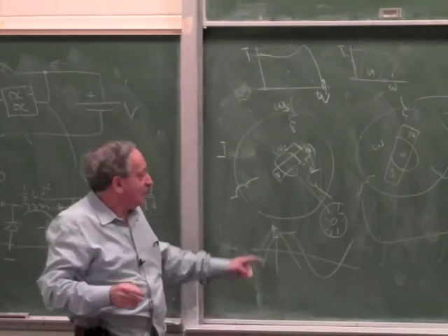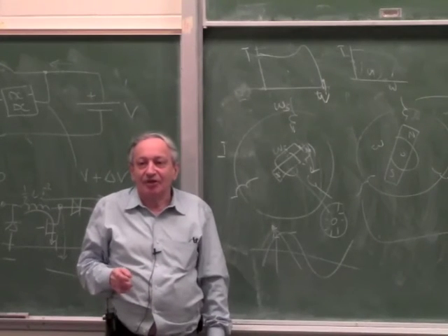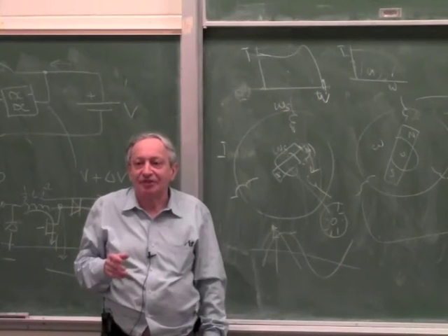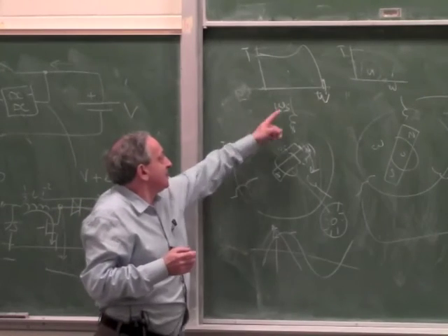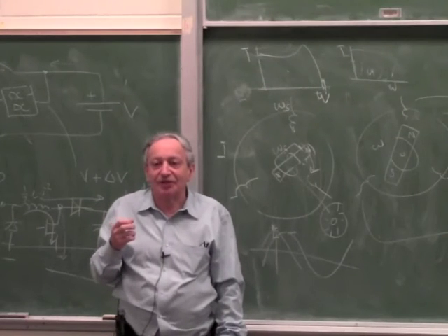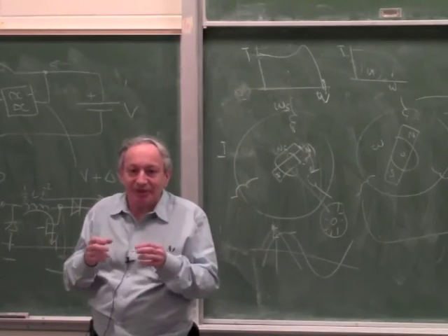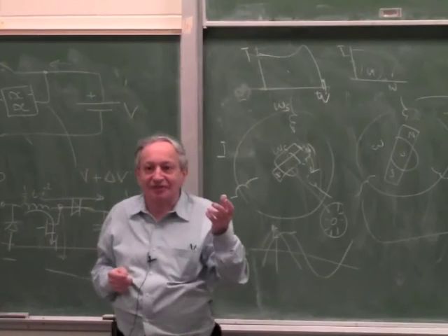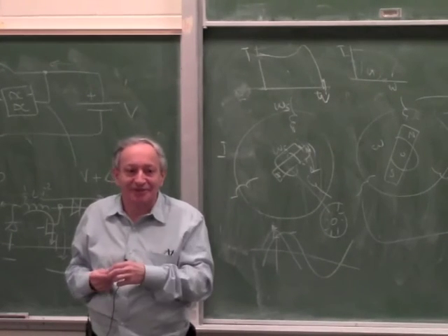So at any given moment, once you know the actual speed of the motor, you generate a rotating field which is slower than the motor, because you can control the phase and frequency of these three coils. So you generate a rotating field which is always, say, 10% slower than the motor. So at any speed down to 0, the armature is always ahead of the rotating field. And because it's ahead of the rotating field, the power flows backwards.